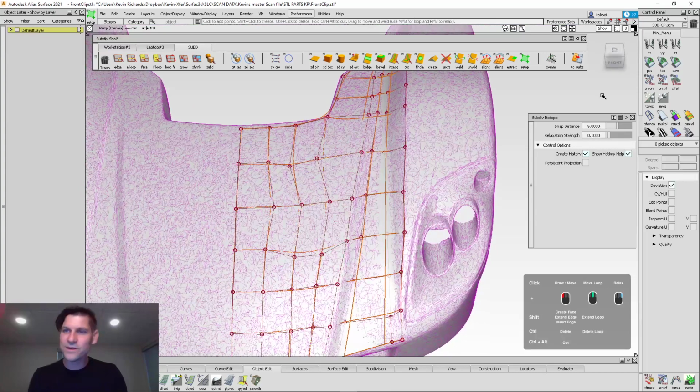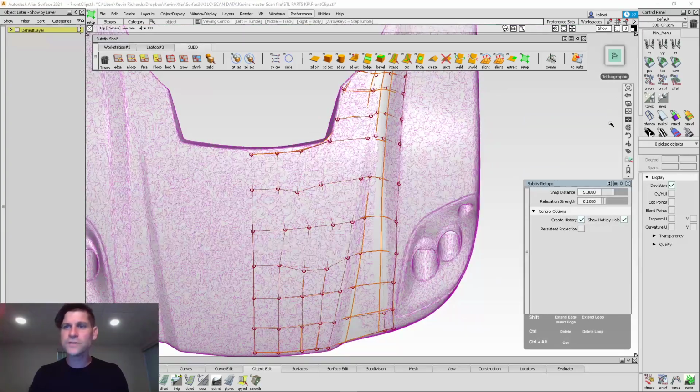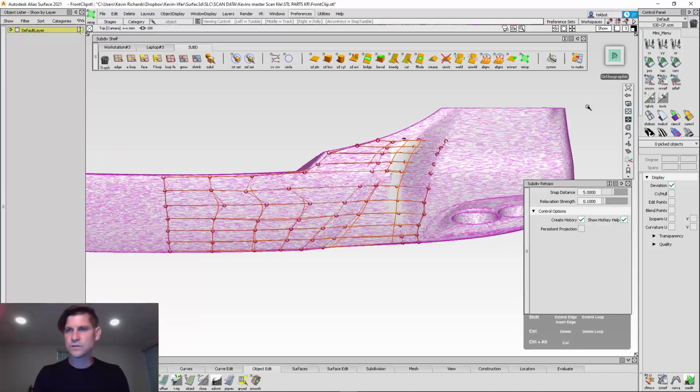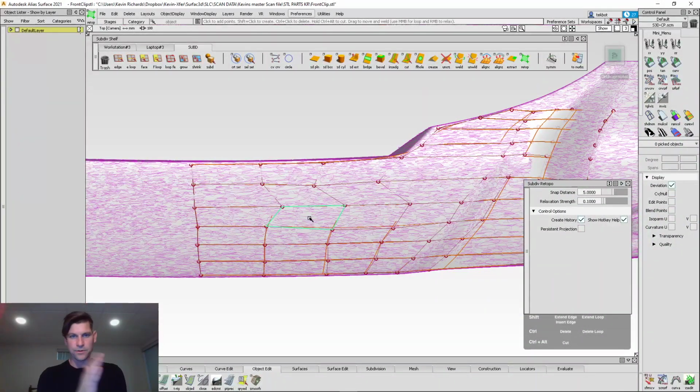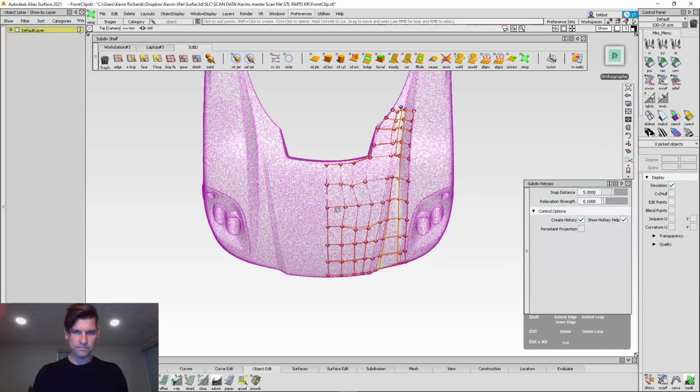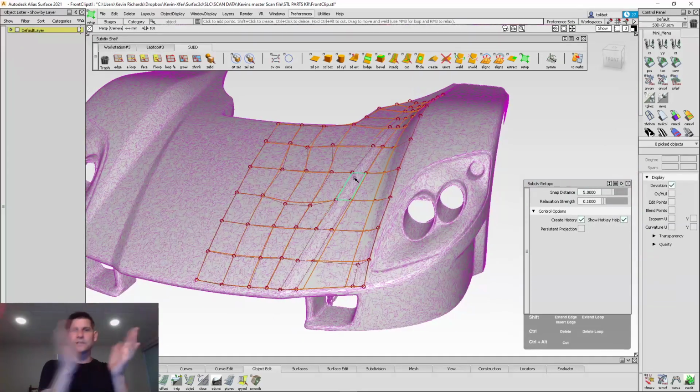So, when I'm Class A modeling, well, when I'm modeling in general, I'm trying to get all of my CVs to flow really nicely. And if we go to top view, often I use tools like this where I'll scrunch these down. So I'm scaling the viewport, not scaling the object, just your window. And clearly you can see the Z pattern that's happening, the back and forth zigzags. And that's not pretty. That's less than ideal, by all means. We'll toggle that off. So you'd have to go in there and adjust the CVs pretty manually.